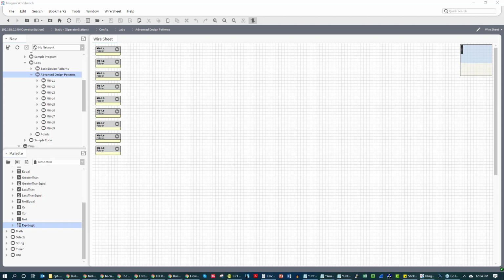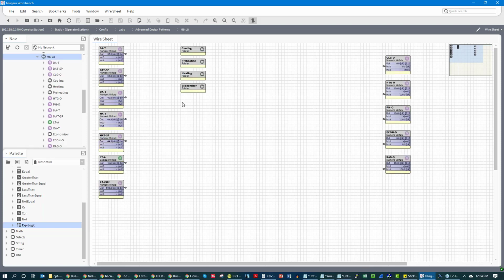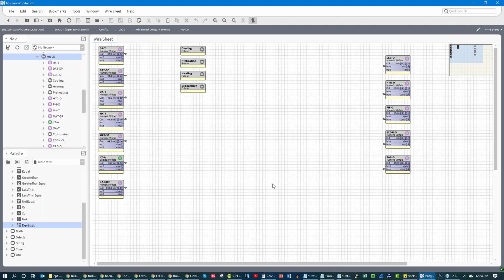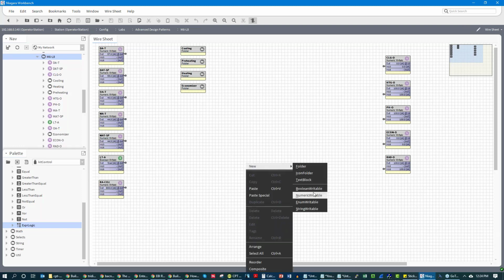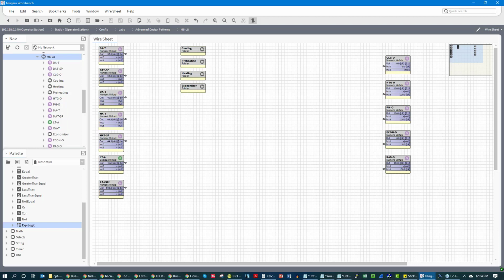Can I talk about point name descriptors like camel case or just using white space? Yeah, so if you try to just use white space in Niagara, because it's programmatic, you will get some goofy results. You will get these kind of wildcard keys and all that jazz. So what I often like to do is go and I will add an object. We'll call this, I don't know, just ZNT, zone temp.